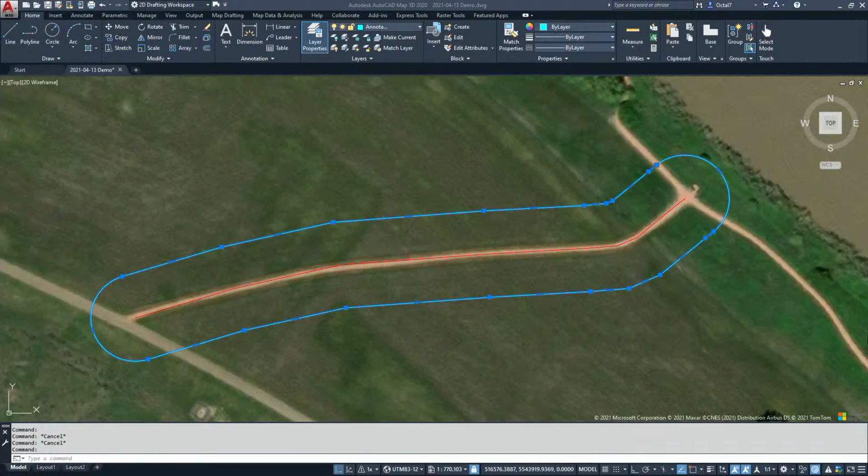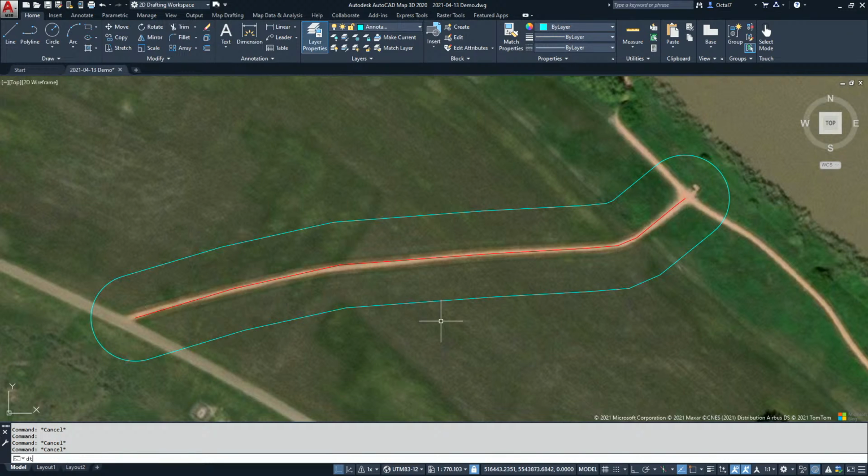All right, so I'm going to move on to the last set of commands here with the TXTMAC and the TXTLABEL. So let's just have a look at that. I'm just going to create a piece of dtext here, and I'll use the justification of middle center, let's say. And I'm just going to put my text here. Actually, let's make this a height of 15, just so it's a bit bigger. Rotation 0.